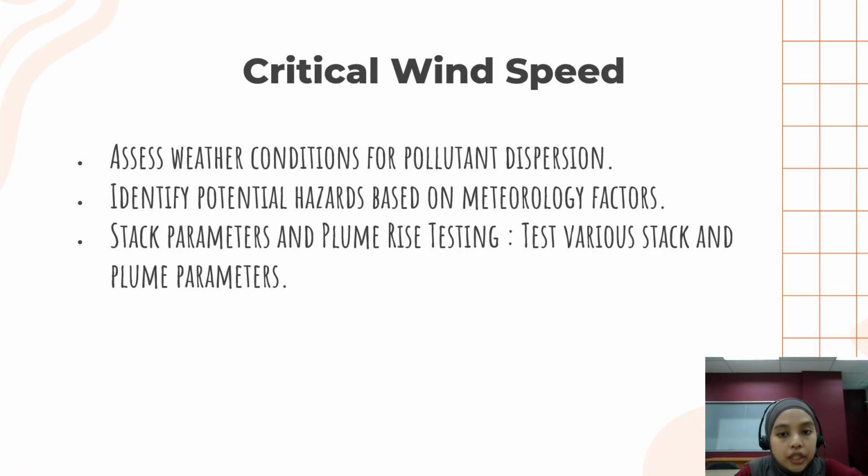So for the critical wind speed, we need to assess the weather condition for pollutant dispersion. Identify potential hazard based on meteorological factors and the stack parameter and plume rise testing, which is we need to test the various stack and plume parameters based on this critical wind speed.